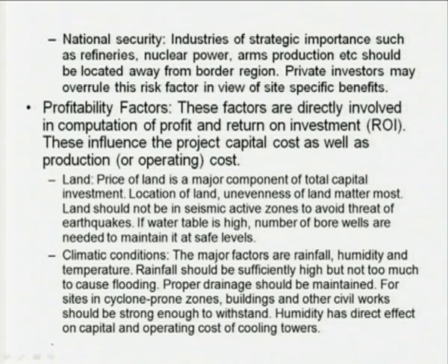The second climatic condition is that of humidity. Okay. The higher the rainfall, the higher is the humidity that is going to be present, okay, especially during the monsoon period. The relative humidity will have a direct bearing on the cooling power, fixed cost and operating cost. Okay. In case of areas with high humidity, the cooling tower may not work efficiently. Okay. So, we have to design the cooling tower taking into consideration the average humidity that is present at the project site. Okay. In case your products are hygroscopic, then they need to be stored in a dry and cool atmosphere, then you have to build special storage facilities that will also add to the cost of production as well as operating cost.